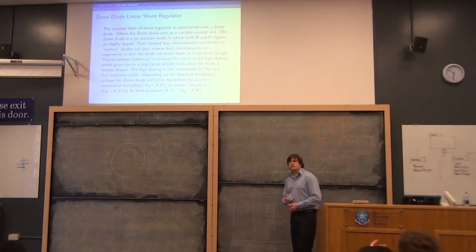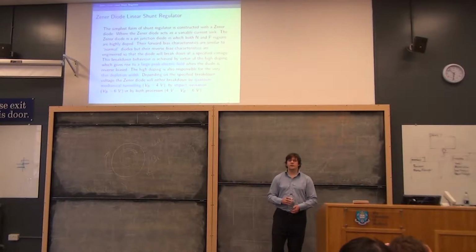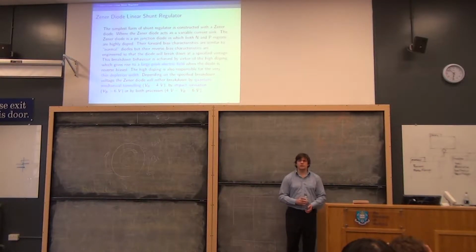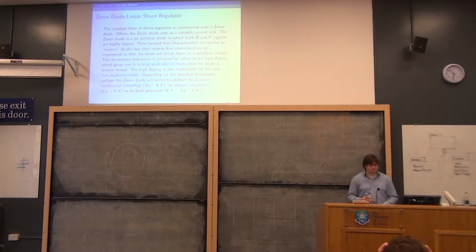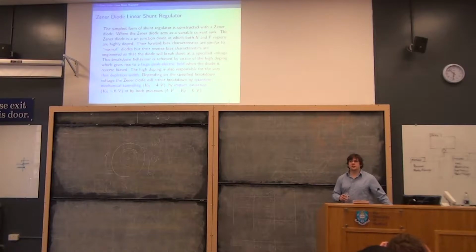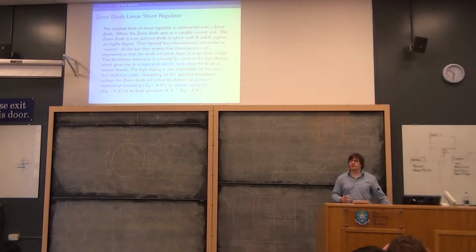And they can go from being on one side of the diode to being on the other without ever having been observed to pass through the diode, which is called quantum mechanical tunneling. If you want to, you can read about it in Streetman. But for the moment, we'll say all Zener diodes are basically the same from a circuit point of view. How they work inside differs depending on the voltage they break down at.